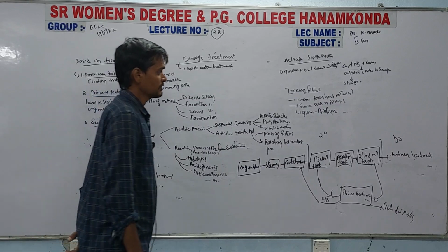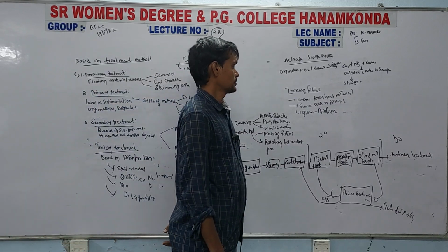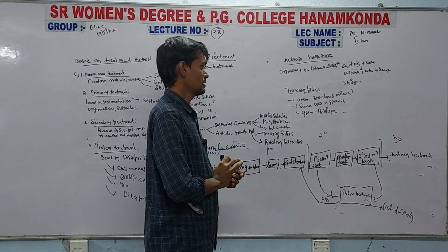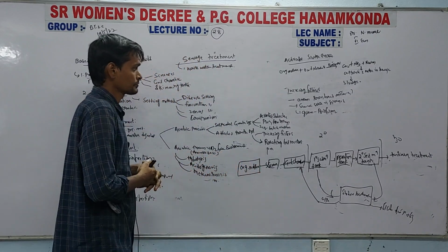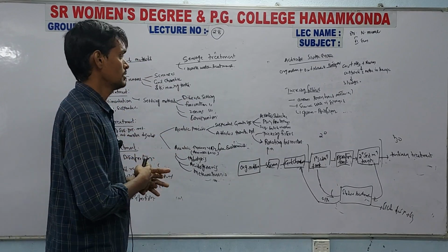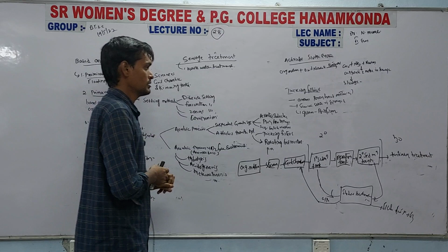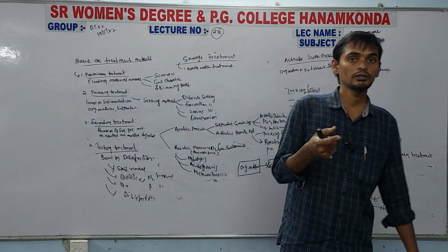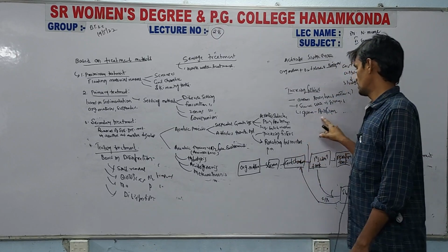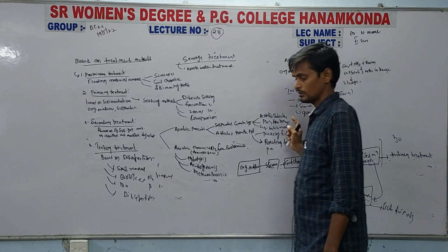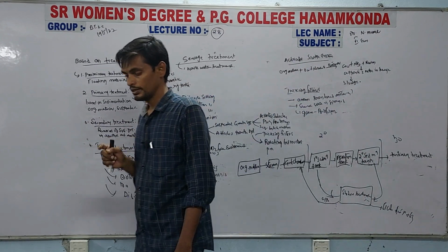Next, trickling filters. In trickling filters, we arrange porous hard material over which the sewage water will be sprayed or sprinkled. After a given time it forms a thin film over the porous material, which is called biofilm. So, this is how we treat the sewage in trickling filters.